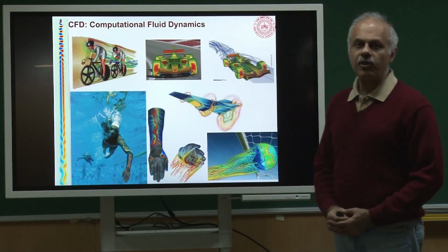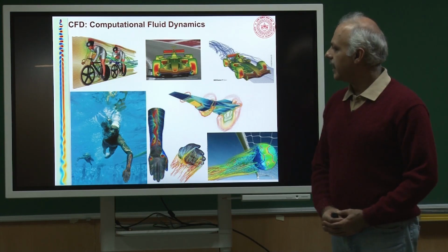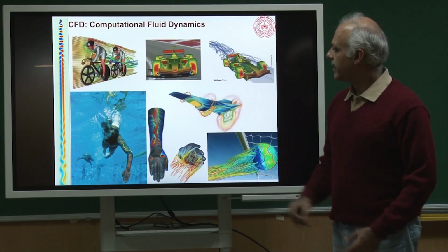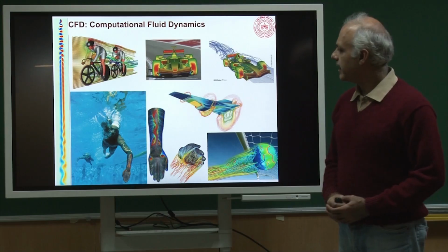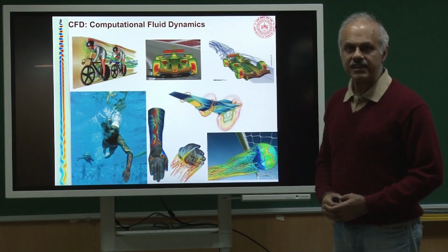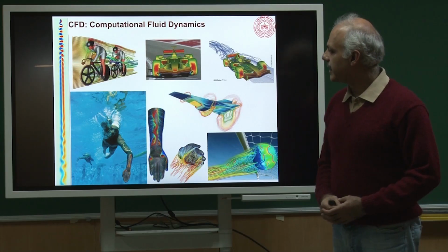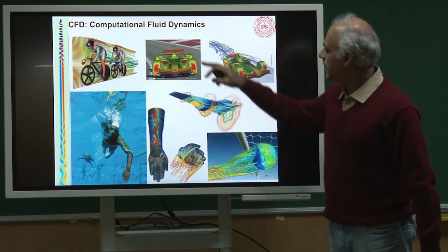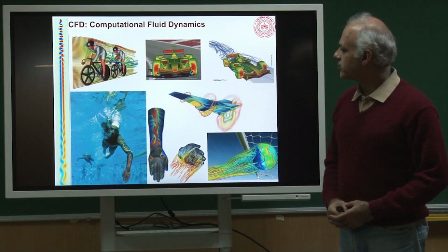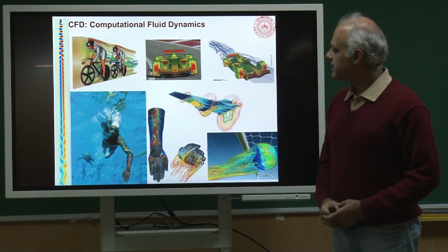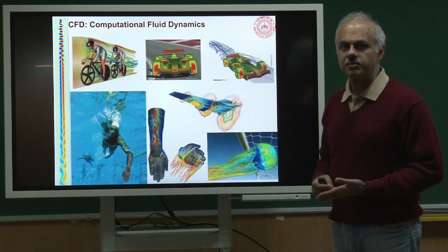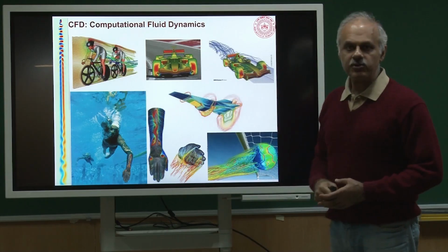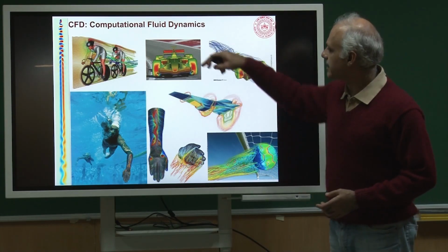The second picture here is the Formula 1 racing car. These cars move at extremely high speed, and when they make a turn, the tires may not generate enough friction in the normal course of design, and therefore the car may skid. So usually an inverted wing is affixed to the car at the rear, and this, unlike an airplane wing which produces upward lift to counteract the weight, actually produces a lift in the downward direction.